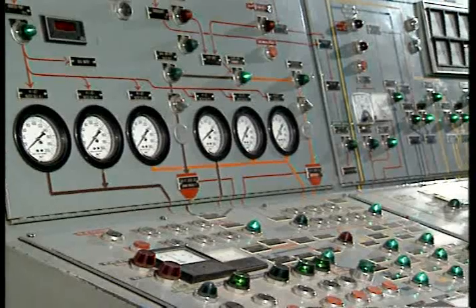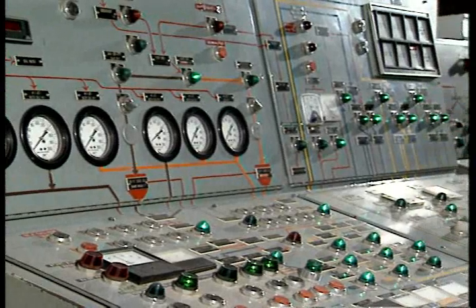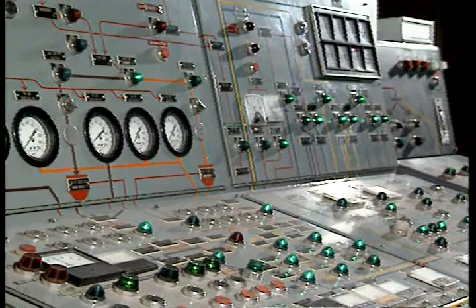But our dust collection monitoring system keeps track of all of the point sources out in the plant. Well, yes, you do have more than one kind of dust control. Sam showed me both a baghouse and a wet scrubber. Right, and each one of these devices needs to be controlled a little bit differently. Baghouses have an engineered pressure drop, and wet scrubbers can be monitored by either manometers or U-tubes.